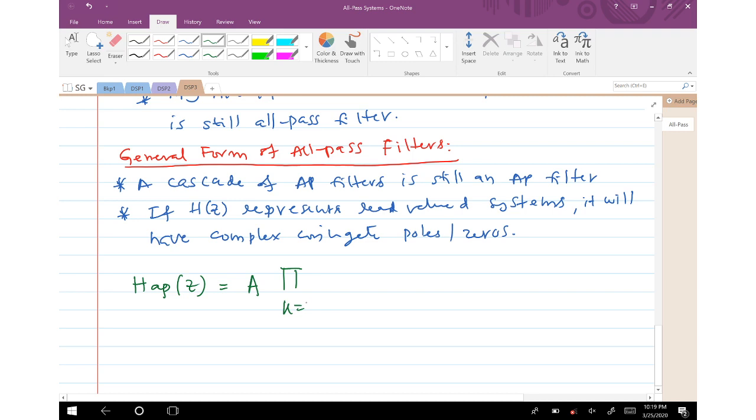So k equal to 1 to Mr, those were the real number of poles that you have. In the denominator, in a similar way, 1 minus dk into z inverse, this is exactly the same nature of function which we considered in our example. And in the numerator, z inverse minus dk conjugate was what we were writing, that being a real pole. This doesn't really matter now, you could put simply dk.